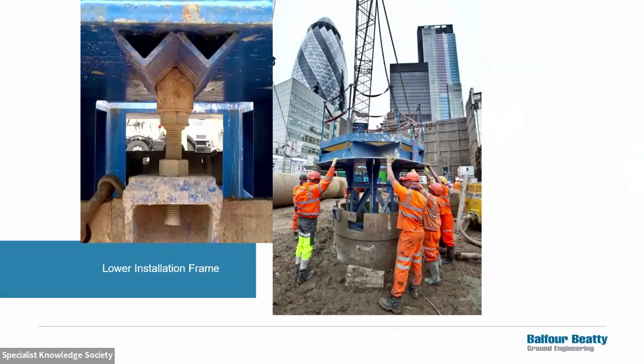So these will be done typically in a rotary bored pile. So you'd have a casing in the ground. You'd have excavated your pile down to the level you needed to. You'd have concreted your pile up to basically your basement level, or your level that you're building your final basement to. You would then put a frame in. So this is a frame that you put in, which is supported on your casing, which would help guide the plunge column in when you want to put it. So again, temporary works considerations are needed about this to be able to get that frame into the right position.